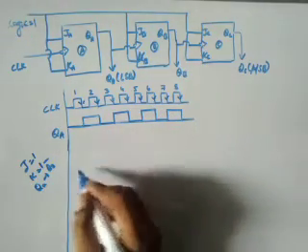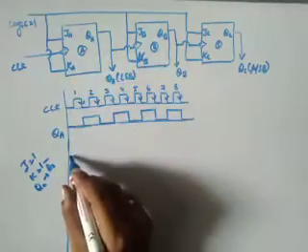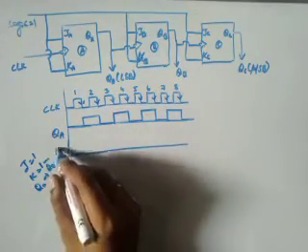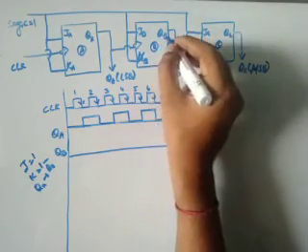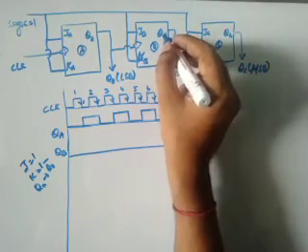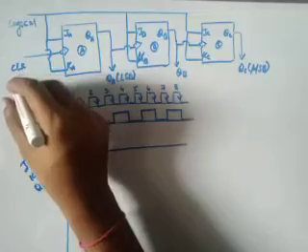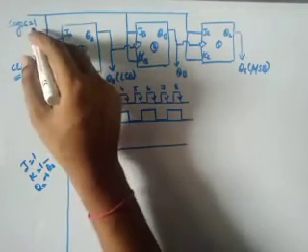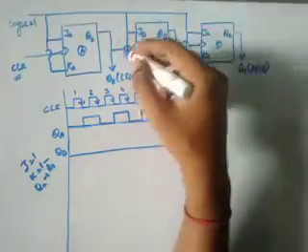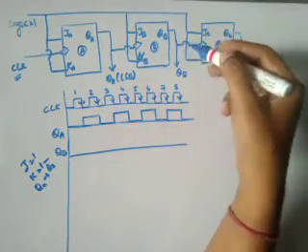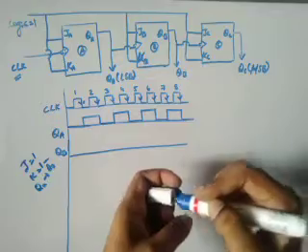Next we have to look at QB. For QB to get its output, don't think that whenever you give a clock pulse here and J and K are 1, all the flip flops will give their outputs at the same time.